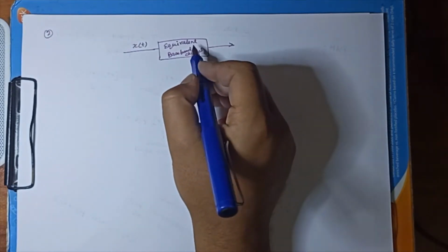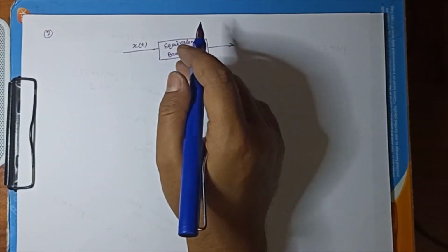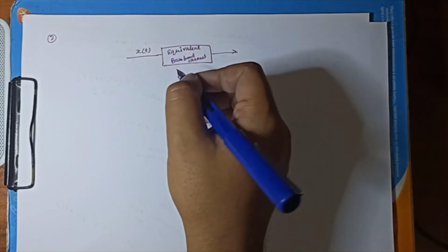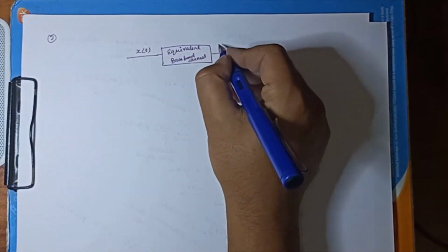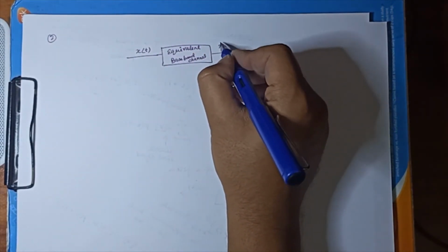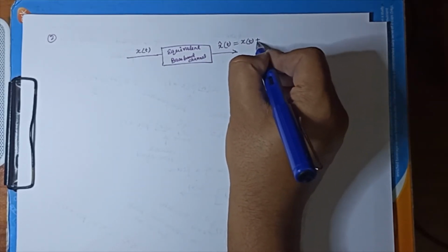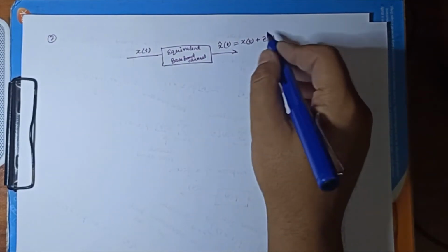Anyway, one thing which will be there is the noise. We cannot help but have some noise here. So whatever you are receiving here, suppose x hat t, that will be basically xt plus some noise process zt. This noise process typically is additive white Gaussian noise.